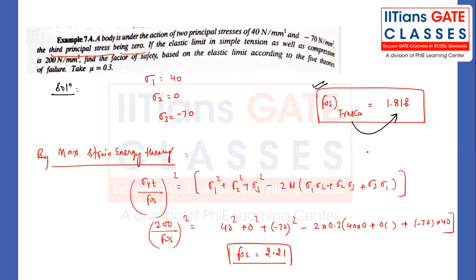But what about the Hencky's theory or maximum strain energy theory? He's saying that you have a lot of factor of safety. Why are you bothering so much? Take less diameter, apply more amount of load, and you fail the material. But Tresca's, no. He is giving you the better results as compared to the Hencky's theory. So among all, the conservative theory will be Tresca's only. Among all the theories of failure, Tresca's will be the most conservative theory. He will be giving the least factor of safety among all the theories of failure. The worst condition will be for maximum normal stress theory only.